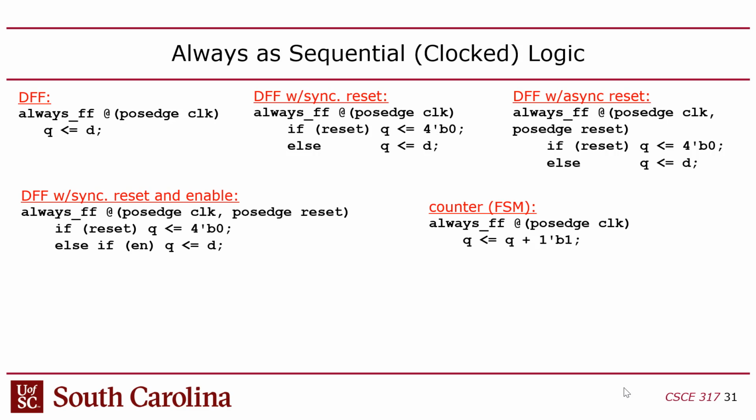Okay? Does it make sense? You might say, well, why can't you read it every cycle? Well, because in order to read it, the NIOS would have to issue a load instruction, right, to load it across the bus, in programmed I/O, and then generally there'd be a couple other instructions there before it could load it again, right? So you can't read it every cycle because you can't issue a load I/O instruction every cycle. There are too many other instructions that have to be put in there.